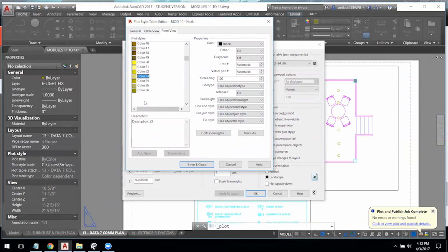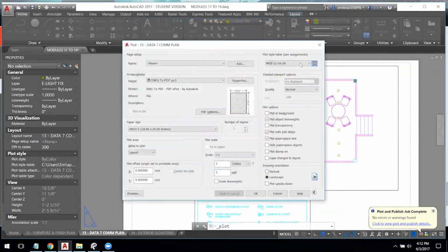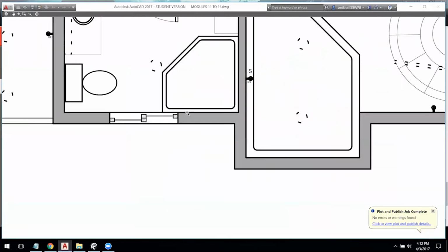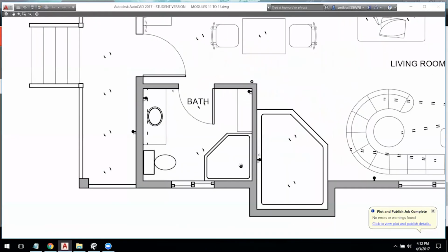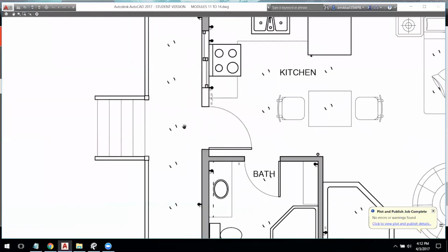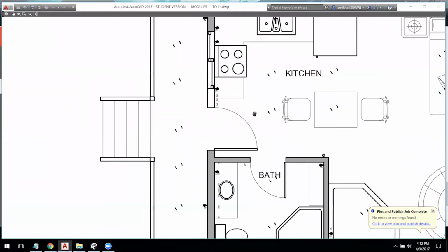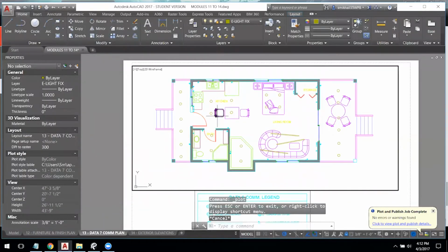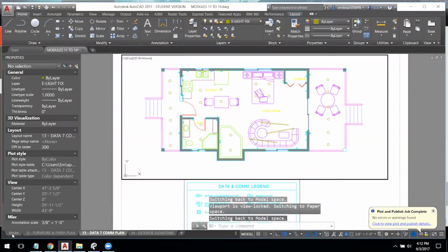And we're going to go to color 130. Let's check this out first. Okay. The dash is a little bit too big, so we want to make sure that we have smaller dashes than this. This is not acceptable. Okay, so I'm going to go in and make it slightly thinner and add more dashes in here. So to load another type of line, you want to escape, go back to your model space in here.